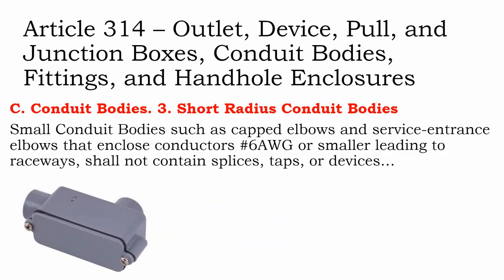Well, the other aspect of when you use LBs is when the customer says, I like the way these LBs look better than a 90-degree bend. You could have a 90-degree bend, but if this were done with a 90-degree bend, it would start bending over here and take up a lot more required space to do an EMT tube with a 90-degree bend, whereas with an LB, you get a nice sharp edge.